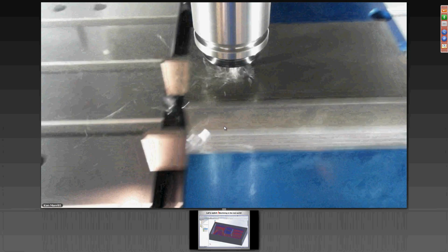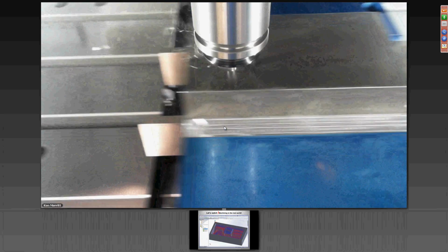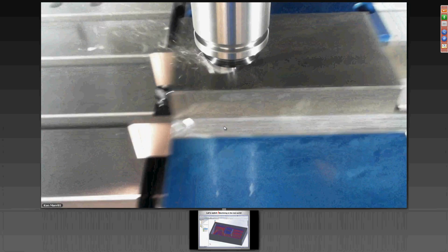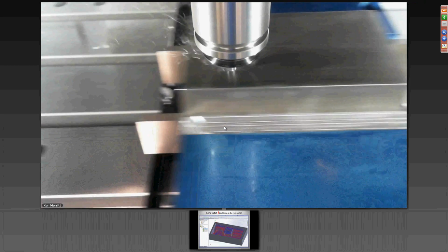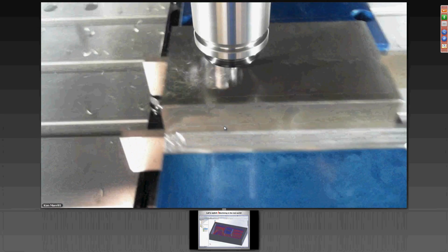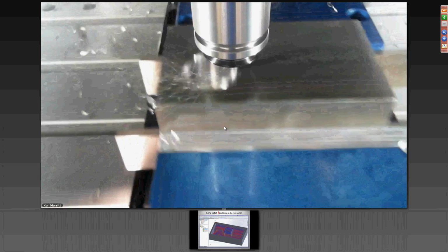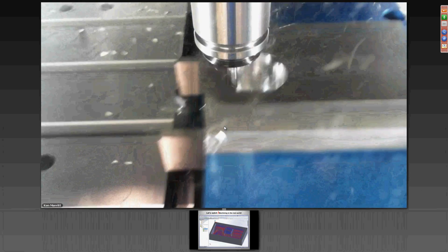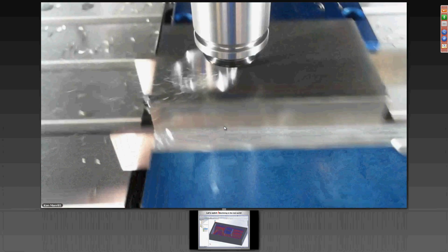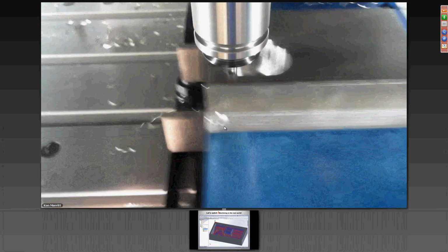Now that we're down at 625 thousandths depth of cut, we're cutting at 10,000 RPM and between 90 and 100, and it looks like 165 or thereabouts, inches per minute. The reason that's a variable feed rate is because we're using what's called a morphing spiral. A morphing spiral is very interesting in that we can run between a range of minimum cutting angle and maximum cutting angle so that the spiral can actually change shape as it grows. It can move from one shape to another without ever leaving the material. As you saw there, we did quite a bit of cutting without the tool having to be repositioned.